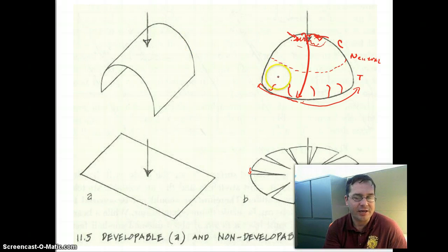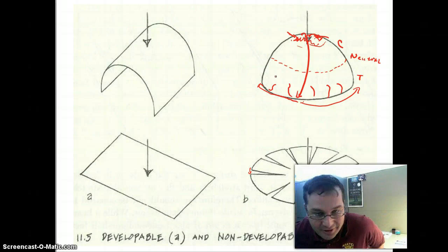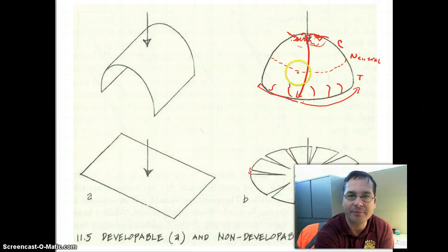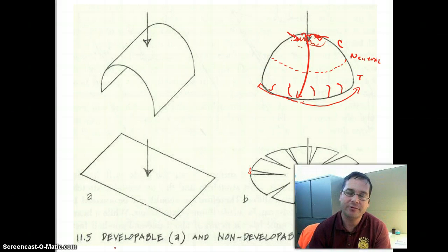There's a tool called a metal shrinking hammer, where if a dent has gone into a piece of sheet metal and it has tensed the metal until the point that it is plastically deformed, a skilled collision repair tech can actually shrink that stretched region back to its original size with some significant hammer work. Of course, nothing in the collision shop is less than $2,000, so we tend not to see a lot of that type of work anymore today. It's just cheaper to replace parts. But the moral of the story is when we're cutting on modern cars, this principle of non-developable surfaces is just as applicable as it is in building construction.